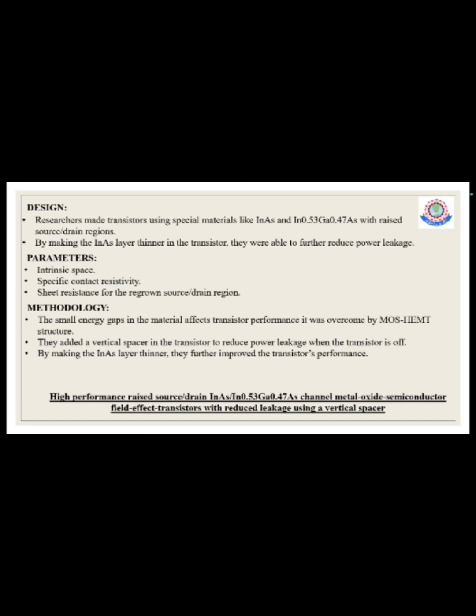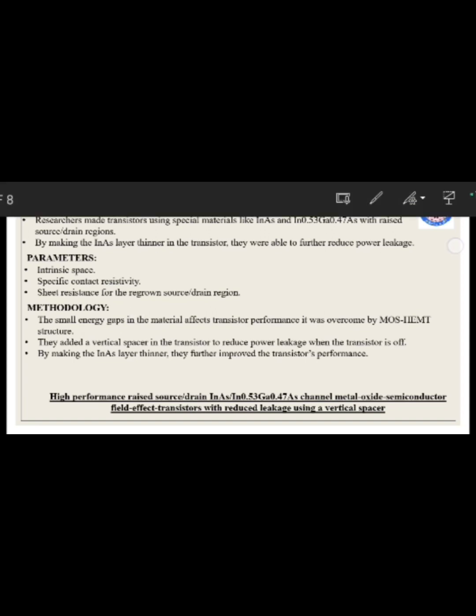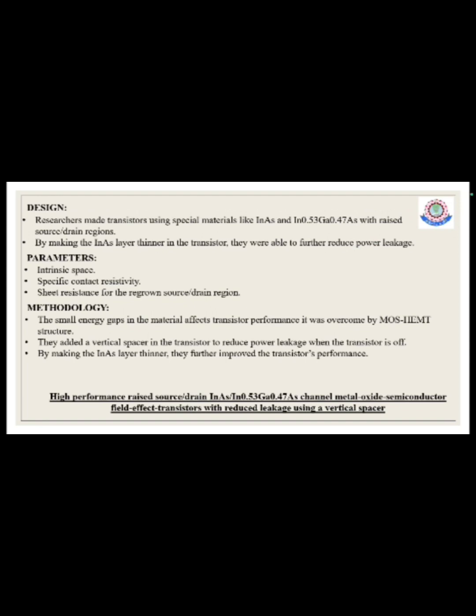So in this paper, they found that using the materials indium arsenide and indium gallium arsenide with raised source drain regions, and by making the indium arsenide layer thinner, the leakage power of the transistor is reduced when it is not in use. The parameters for this paper are intrinsic spacer, specific contact resistivity, and sheet resistance for the regrown source drain region.